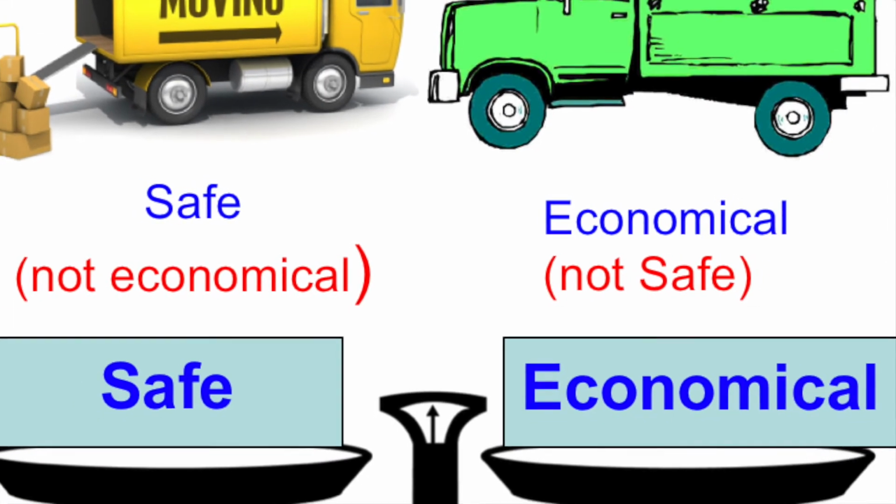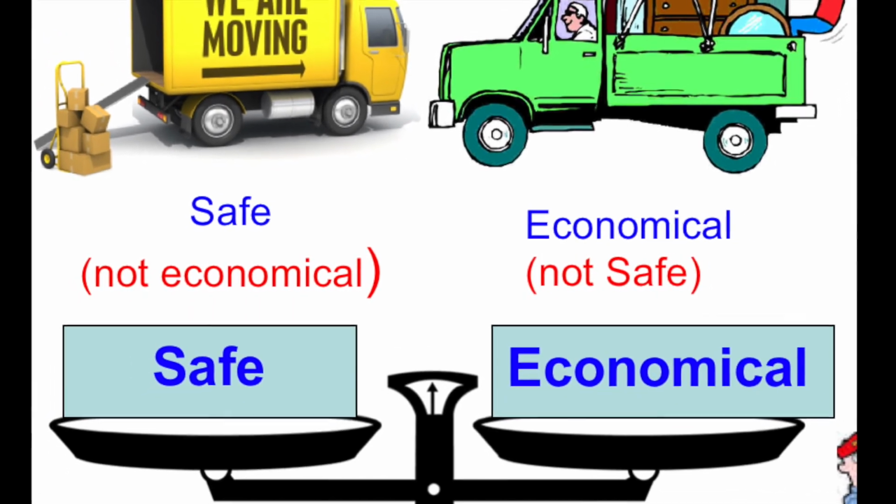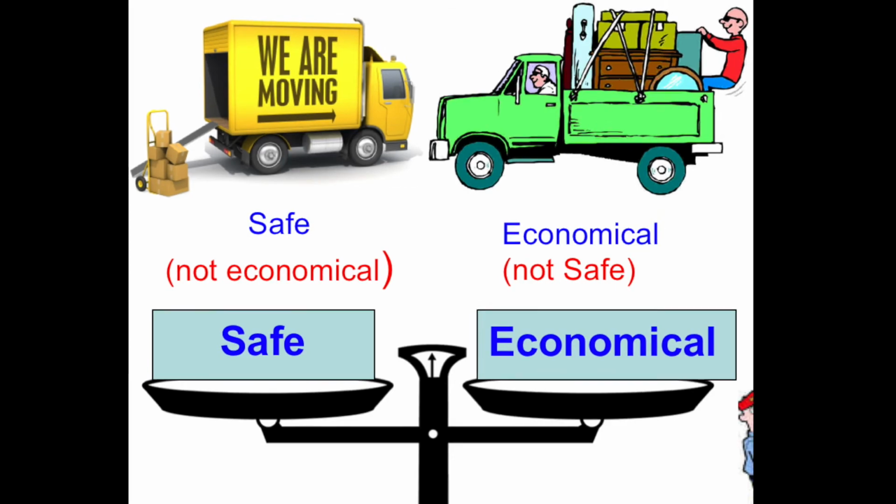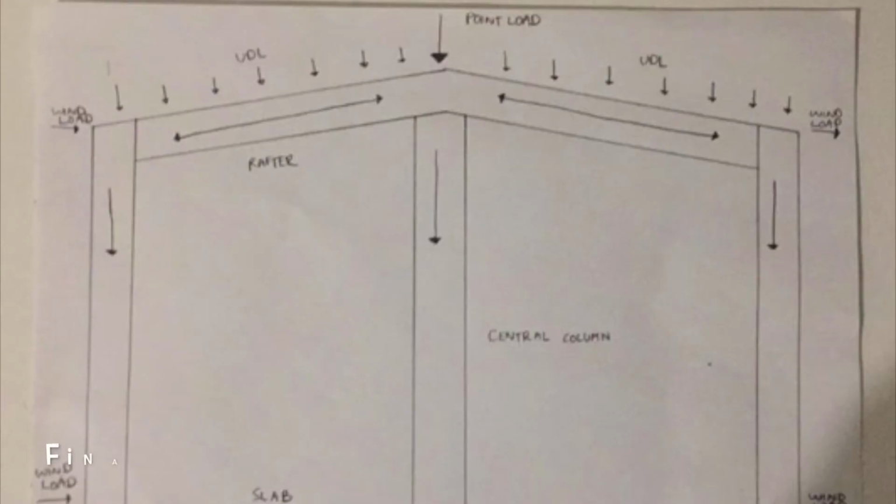Finally, we designed the vertical column members that support the actual compressive load being transferred from the roof to the footing. As they are pinned connections, lateral load does not need to be considered. The column design was found on the first try, with a section of 100 universal column 14.8. It is noted that this design is not very economical due to the additional capacity, but it is still the smallest column and still safe for the central column.